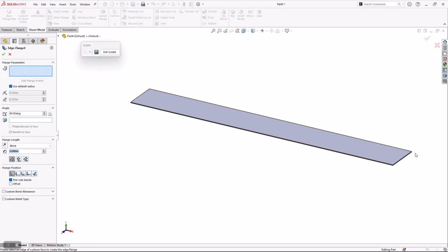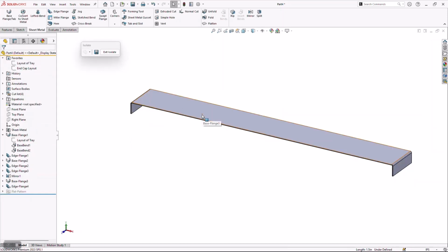Now to do that, I need to put a couple more return flanges on the ends, so that way I have a place to spot weld. I want these flanges to maintain the standards that I've already set up. So again, leveraging the equal sign gives me the ability to grab that global variable. And I want to make sure that that flange material is to the inside of the part, so that way my handle stays flush to the inside of the end caps.